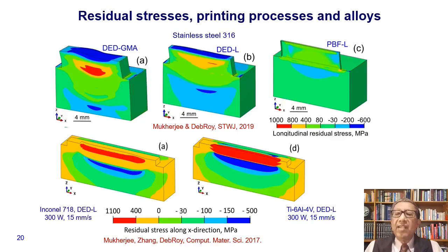Presence of large amounts of residual stresses is an important issue in additively manufactured parts. And since mechanistic models can give us very accurate three-dimensional transient temperature fields, these data can be fed to commercial codes like Abaqus or ANSYS to provide very accurate calculations of residual stresses and distortions.